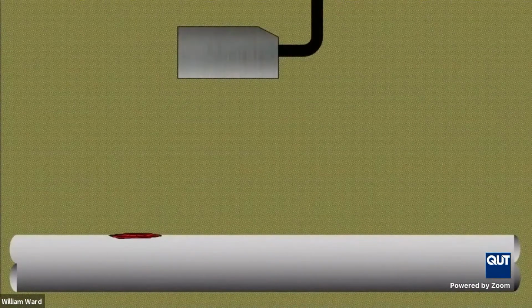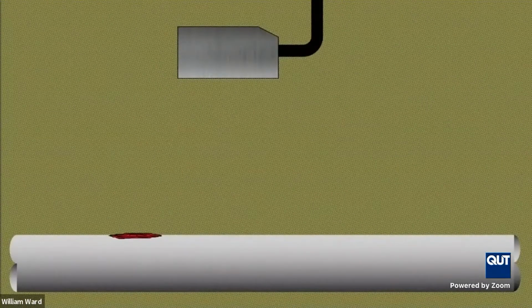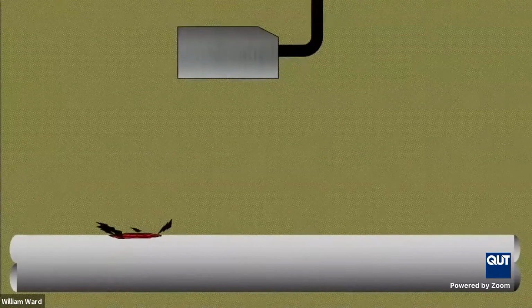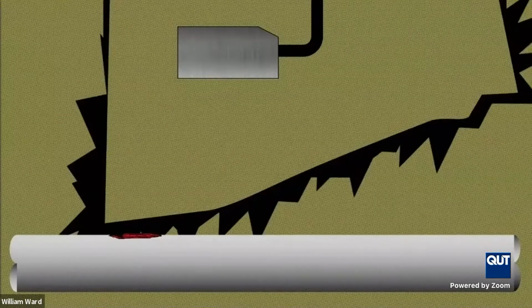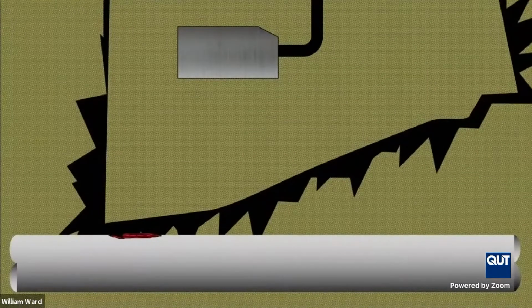So let's talk about a tool you probably are familiar with, which is appropriate to catch the physical beginning of damage. And that would be some form of acoustic emission. This is not an area I have a great deal of expertise, but I did want to point out that if you are using something like acoustic emission, you'll be catching physical damage as that reinforcing steel undergoes expansive corrosion. And that's right at the end of the durability cycle.